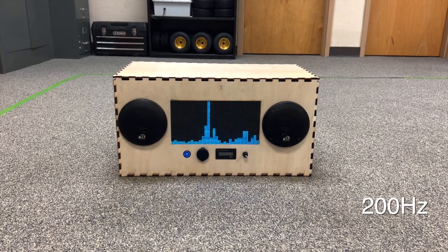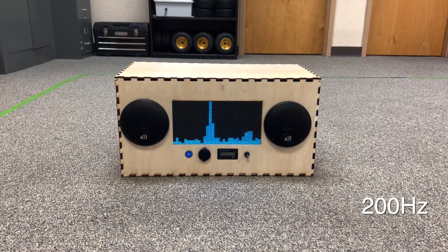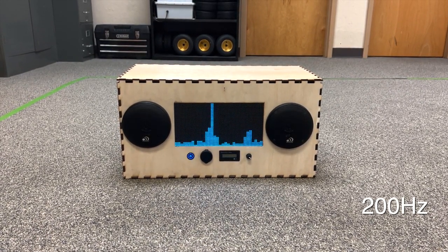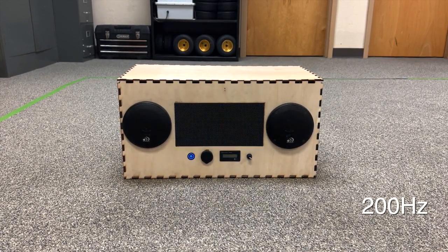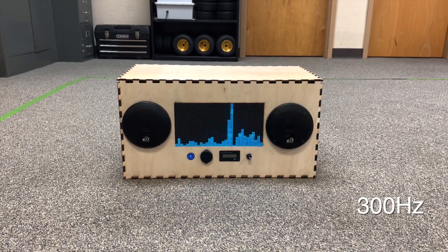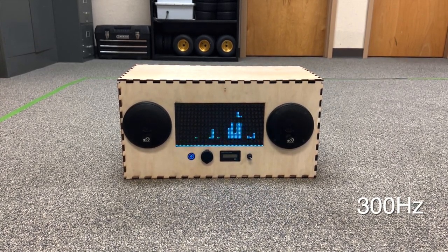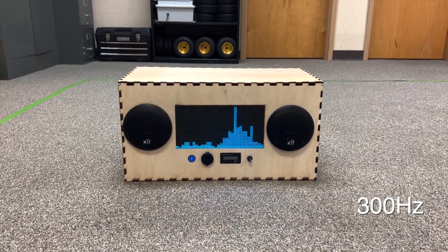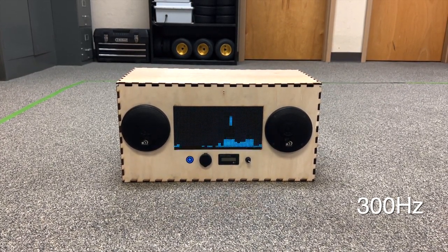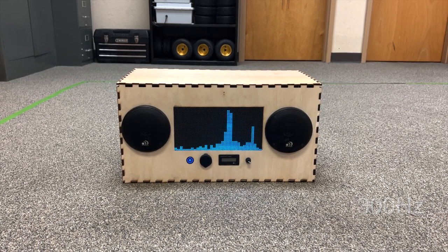matrix, as we have the ability to display a range from 0 Hz to 460 Hz, because our Nyquist rate is 920 Hz. We choose to use this average FFT mode in this demonstration to allow for more precise data to be shown compared to the rapidly refreshing FFT. Through this test of 4 frequency ranges, we find that our matrix displays the data correctly without any error.